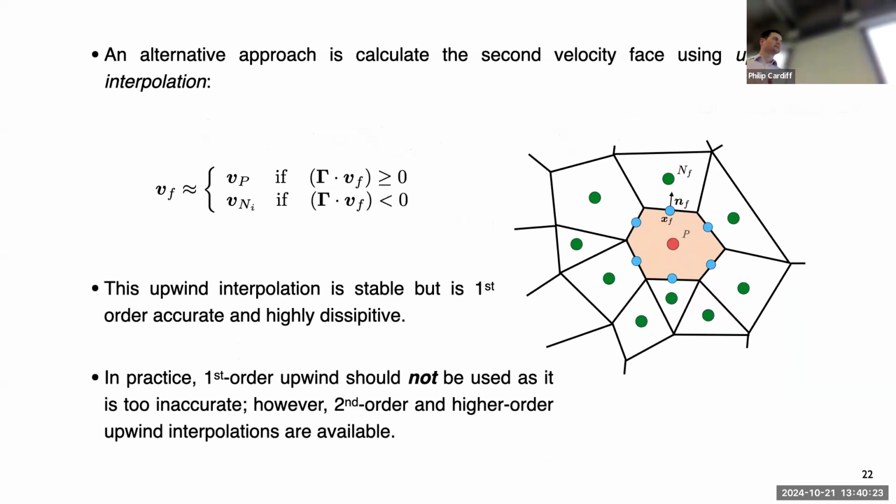What does that mean? It means that when you use upwind for this convection advection term, it will reduce the order of accuracy of your entire method to first order, which means if you halve the mesh spacing, the error will halve. That doesn't sound that bad, but it's actually pretty poor. It means you'll need very, very fine grids to get to the true solution if you're using the first order method.